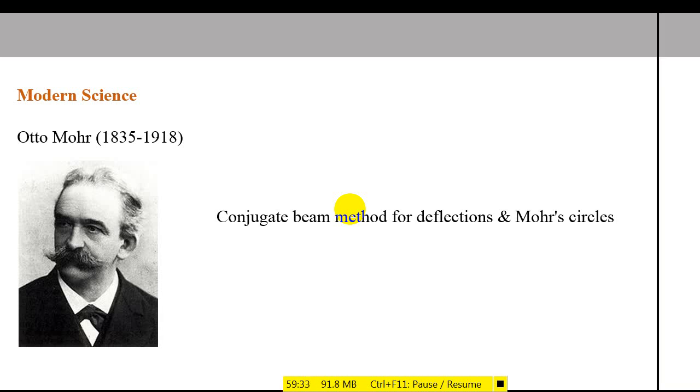No. So vibration, cracks and deflection are 3 main service limit state criteria that govern the usability of a building. Serviceability of a building, or of a bridge, means usability. Can we still use it?